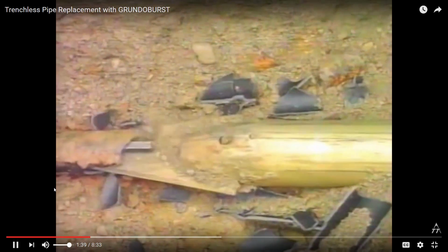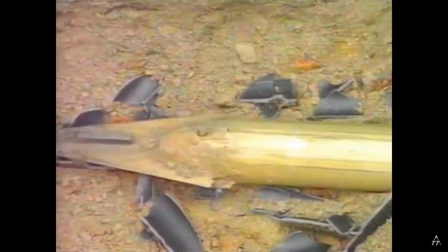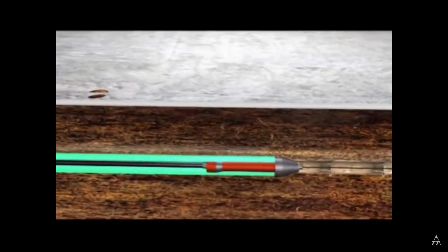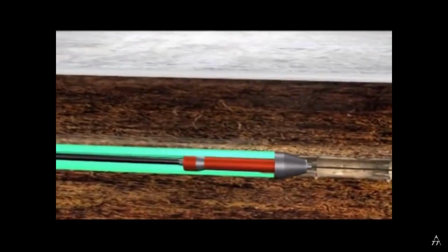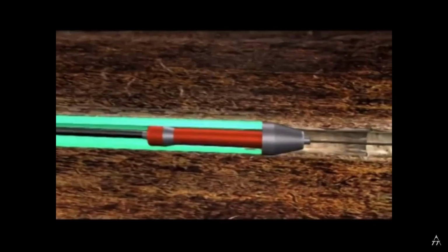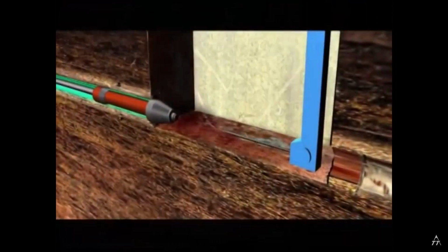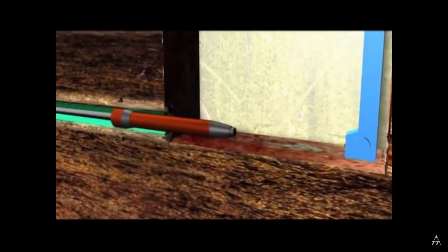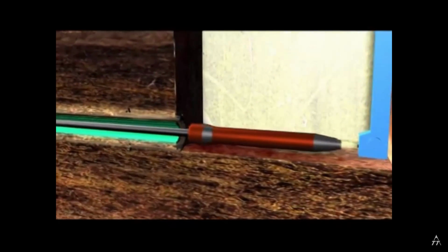There are two different pipe bursting methods, dynamic and static. When dynamic pipe bursting is being applied, a pneumatic hammer or ramming machine is propelled through the old pipe with the assistance of a winch, which performs the actual pipe bursting operation, whilst simultaneously pulling in the new pipe size for size. Upsizing of existing pipelines is also possible.